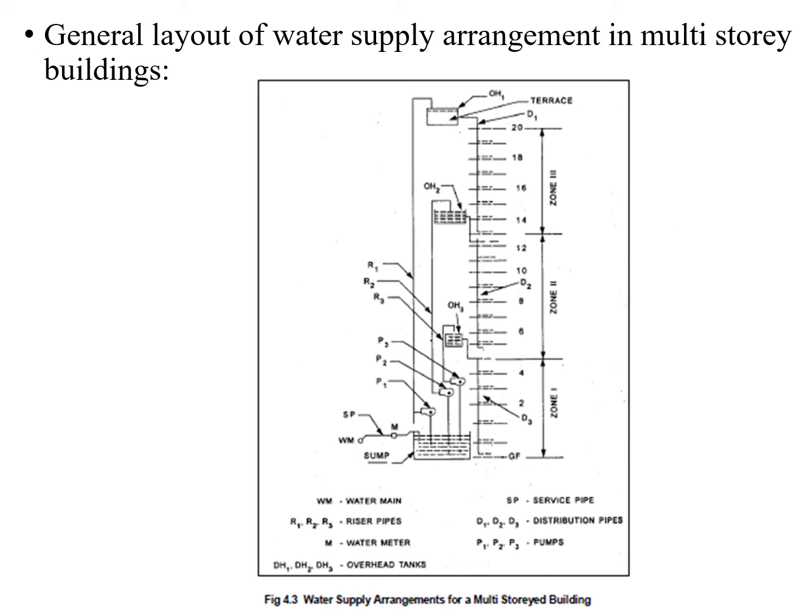Again, this is the case for a multi-story residential building. See, if the height increases, the number of people using the system increases, that is a vertical increment. So this increases the capacity of water to be stored in the water tanks. For this, water tanks at different levels are maintained, and you can see this. I have OH1, that is overhead tank 1. Overhead tanks 1, 2 and 3 are at different levels for the different zones. The zones are divided depending upon the height of my building.